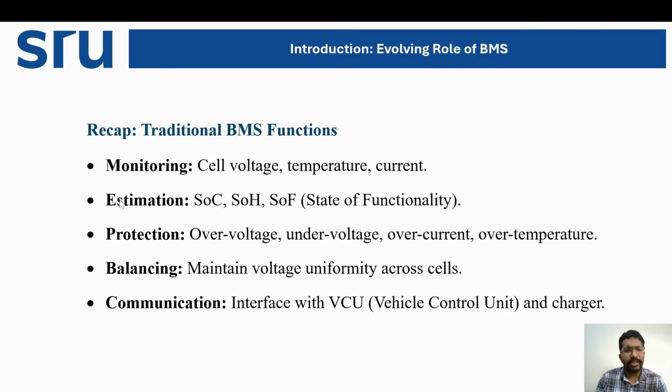Then other things coming to the protection part. So over voltage protection is there, under voltage protection, over current and over temperature. Over temperature is handled by a subsystem within the battery management system, that is called the thermal management system.